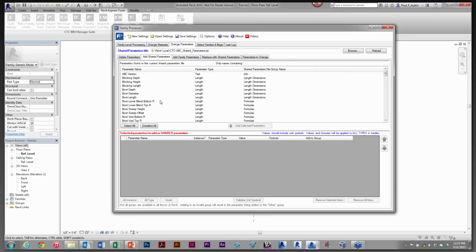So for example, what my client and I were doing is we were creating a text parameter in all of the families that we're creating and giving it a version ID. So this way, we know inevitably users are going to have comments, questions, and issues, and we're going to go back to the family files and make changes. So when they get updated in the library, we just wanted some easy way to tell whether or not users were using an old version of the family. They come back and say, oh, the door doesn't behave properly, or the leaf isn't doing what it's supposed to do, and we say, well, we fixed that, right? Then we can look at their family and see, oh, you've got the old version. It's just a way for us to troubleshoot that.